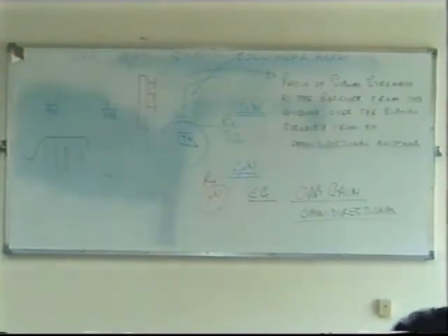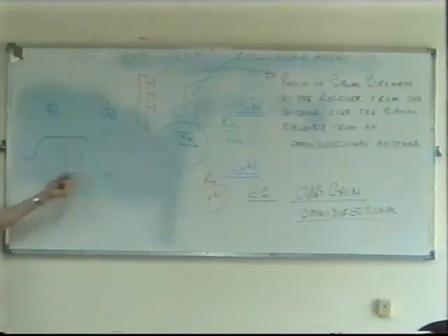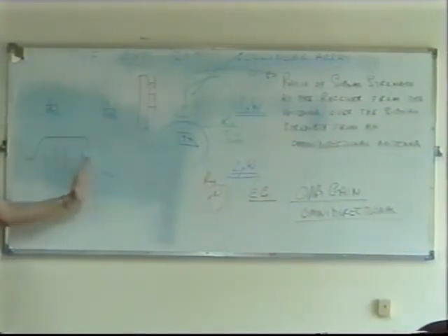So that they transmit the complete band. That's right. Band pass filter. Well, it is like a bandpass filter in a sense, yes. But it doesn't matter to the antenna. You see, an antenna will be designed to radiate most efficiently at a certain range of frequencies. You can get VHF antennas, UHF antennas, microwave antennas, and they'll be designed to operate over a certain band of frequencies. And providing your transmitter channels fall within that band, it will work.